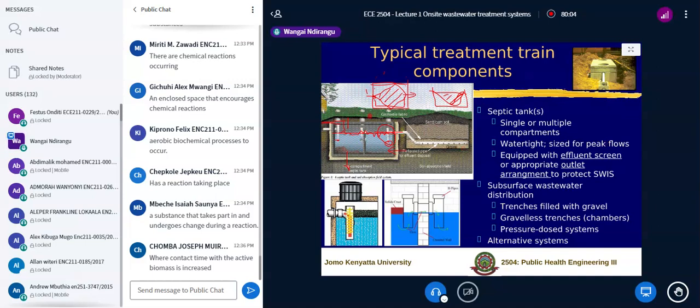So in terms of the plan, 50% is lost, and in terms of the depth, 50% is lost. That means effectively only 25% of your designed volume is actually effective. So if you had designed this for a 2 days detention period, it actually does it in 12 hours because of the configuration. So there are certain things that we do to change that scenario.